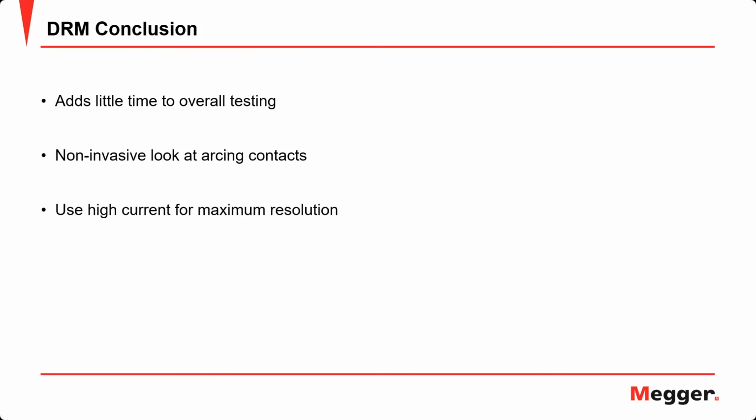It's good to use high current for this test for getting maximum resolution. And you can use previous results to do trending and notice the difference in the length of the arcing contacts.